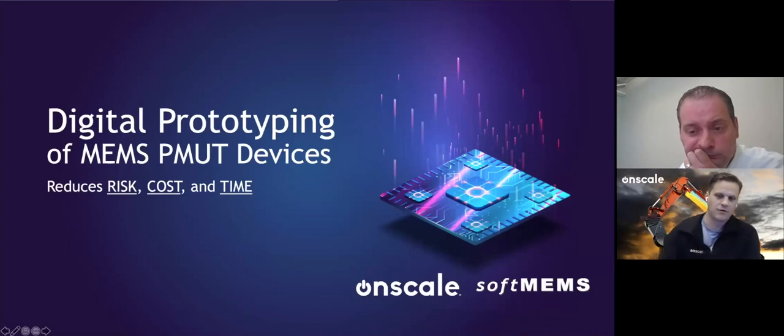So that's what I refer to as tuning a simulation tool. If you don't know what your actual parameters are, you just do a parametric sweep and you find the closest match. And if you can get within ±5% of the actual experimental performance, that's usually good enough. Okay. All right. Very good.